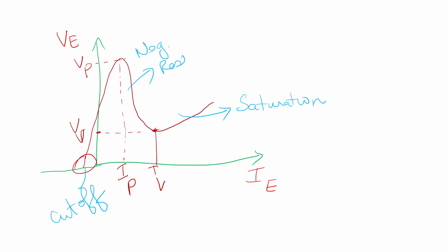The unijunction transistor is on now. When the voltage across the capacitor decreases below the holding point of the PN junction, the UJT turns off and no current flows into the emitter junction. So once again the capacitor charges up through resistor R3.